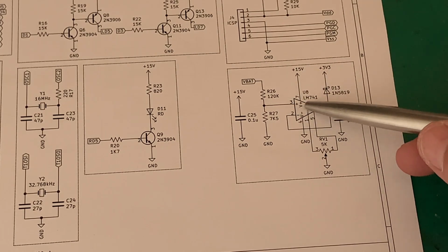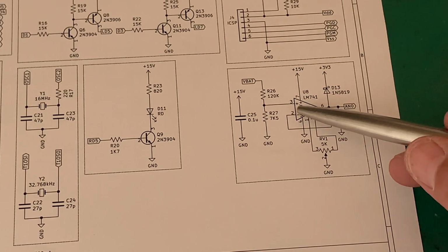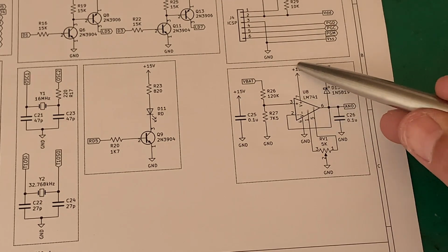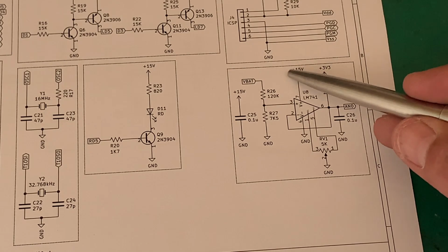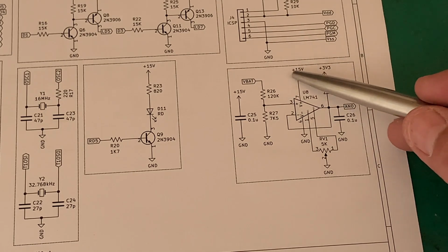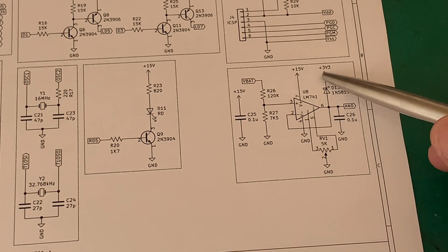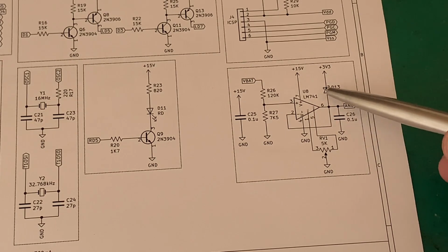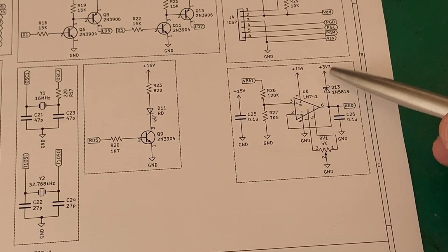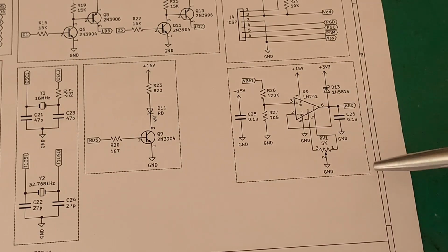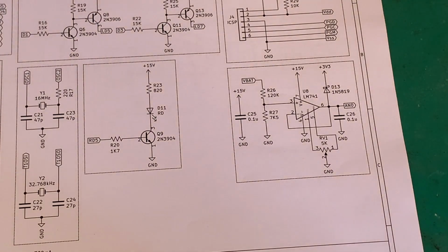Why? If something goes wrong, we're powering this with 15 volts. For whatever reason, if that shoots up, it can go to that 15 volts. Well, not quite. Remember, we said it can't go rail to rail, but it can go close to that 15 volts, and that will destroy our micro. So what we're doing is clamping it in case of a fault here. This voltage here will be 1 diode drop higher than that 3.3 volts. So maximum, let's say with a 1N5819, 0.3 volts, so 3.6 volts, which is safe enough for our micro.